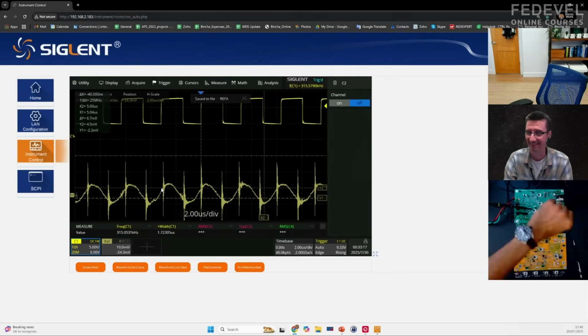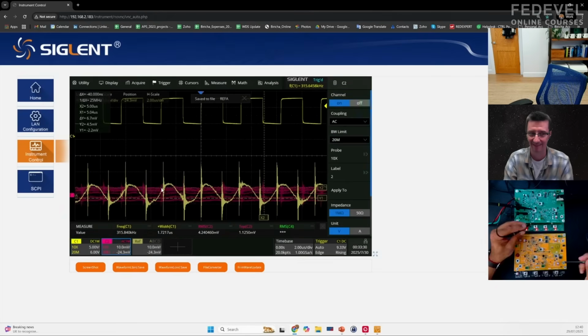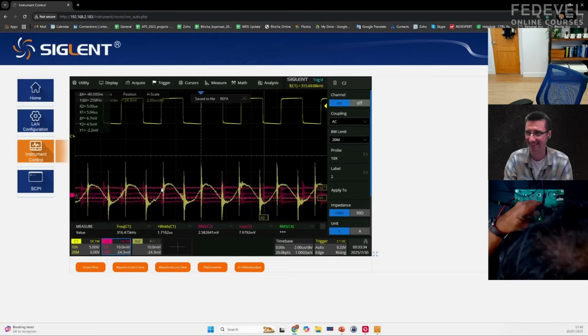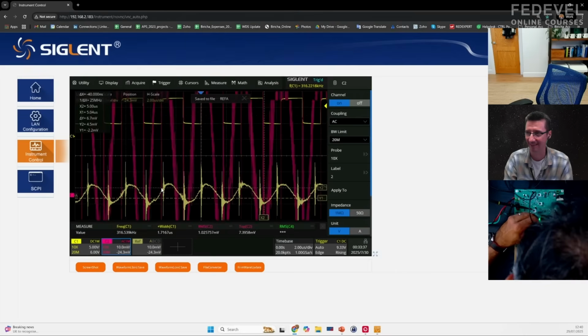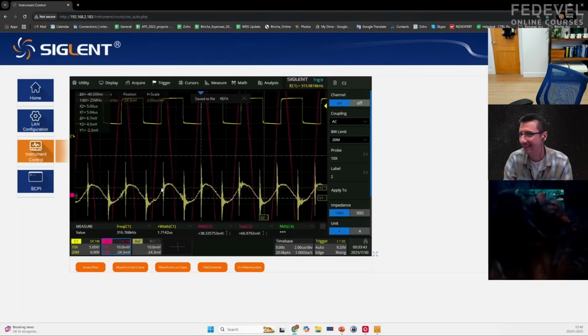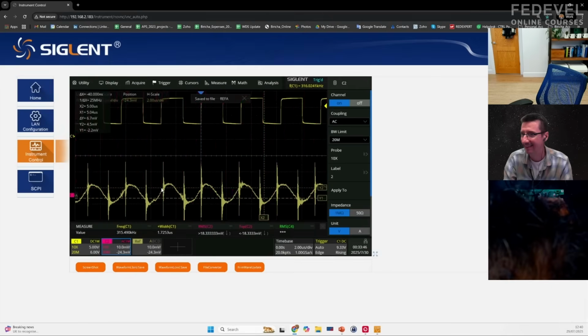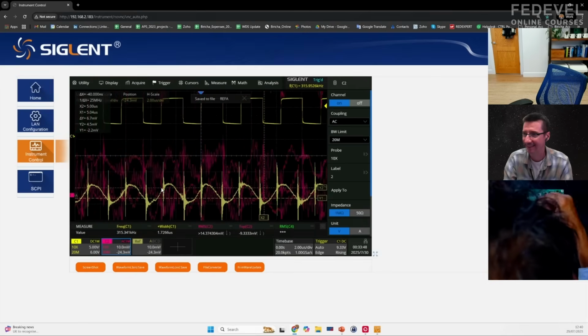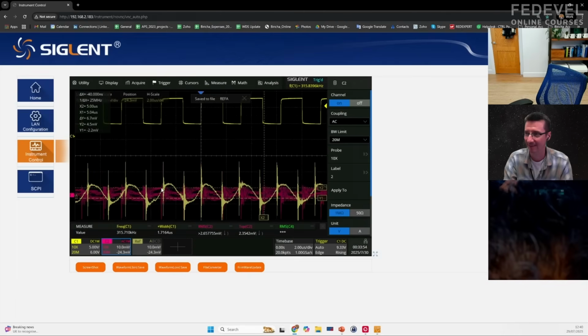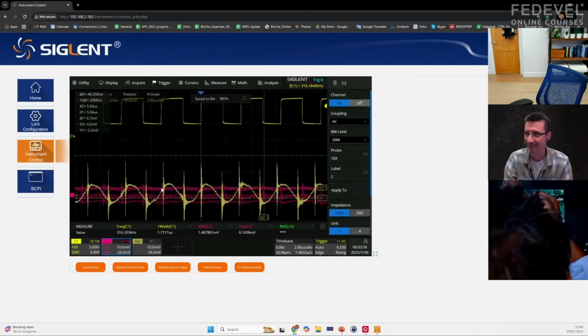So this is a constant on-time power supply, right? Identical to this one. The difference is that this one has got electrolytic. So let's have a look at the ripple on this one. I'm curious. Look at that. Can I make this a better measurement? Bear with me. I'm going to try and find a better place to measure it because it's very, very noisy there. So there we go. That's my switching frequency.